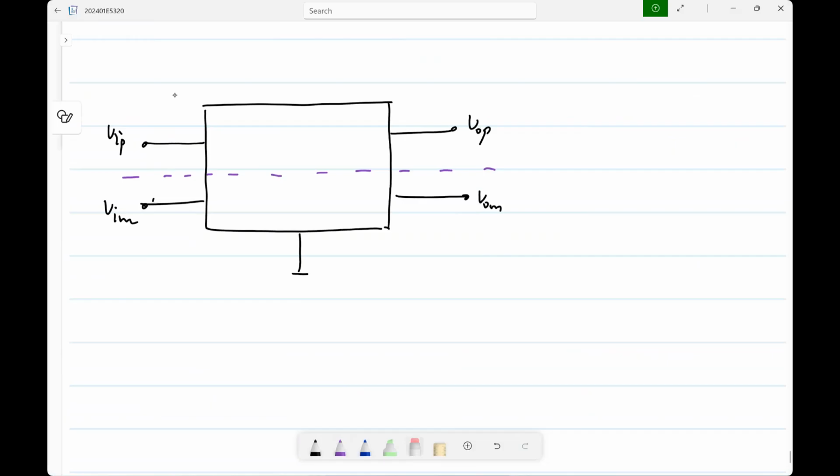Okay. So now when you have fully symmetrical circuits, there are shortcuts to analyzing them. It's not quite a shortcut. Actually, if I didn't give you all this motivation about fully differential stuff, you could think of it as some circuit with two inputs and two outputs. How many possible transfer functions are there? 4, from here to there, there to there, there to there, and there. Okay. But because of symmetry, some of these become redundant. Okay. And functionally, what you want is from the differential to the differential one.